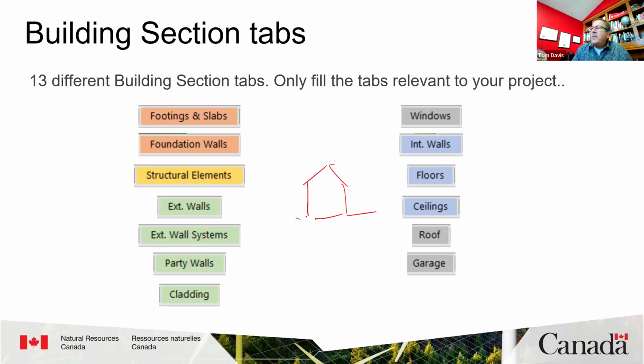Here's a home with a basement. You know, we've got about 20% of the energy loss through basement walls and floors. That needs to have continuous insulation. Our walls are about 40%, and our roof can be about 40%.